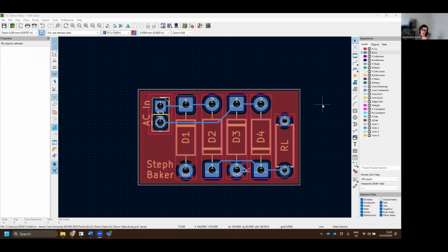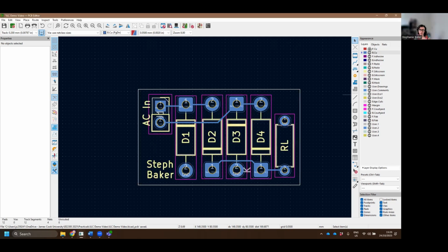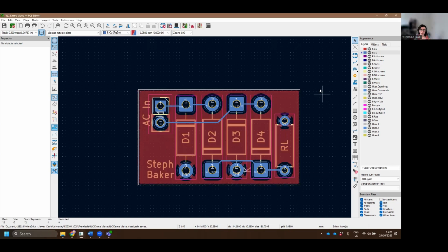All right, and then we're back sometime later with our cute little PCB that's now ready to actually export and take over to JLC to check out how it looks manufactured. Before we do that, we probably want to also have a look at how it looks on the 3D design view. So a few things that are different about this board compared to the first time we did it for the milling machine. I've routed everything on the bottom again, but I've actually made my ground plane the entire top layer. So no traces at all on the top layer, just ground plane, which is really, really good for signal integrity. And then we also have some silk screening done. So all of the actual yellow stuff that you can see, if I turn off my red copper, that's all actually going to be part of our printed design now.